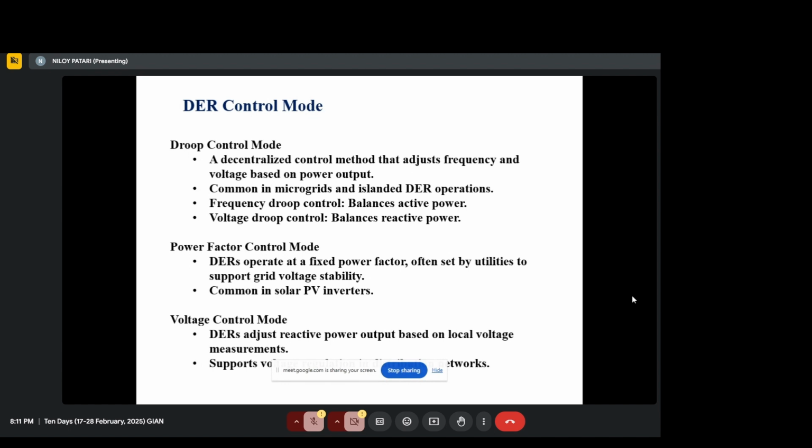In any feeder model, most of the time you'll find huge capacitors at the substation side, whose main function is to correct power factor. Then there are some capacitors at the periphery to improve the voltage. But I'm just giving an example.